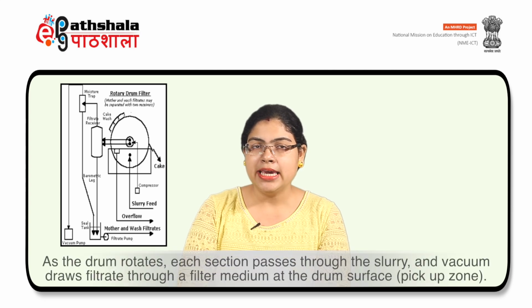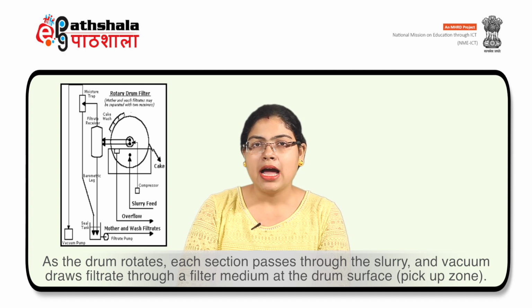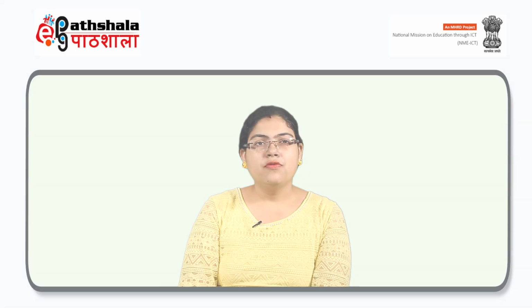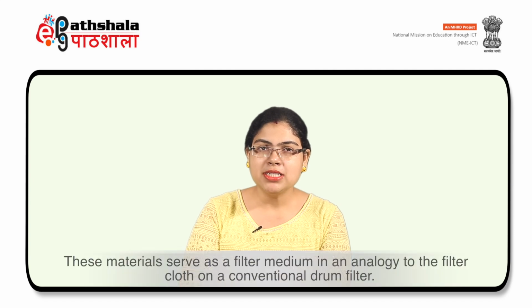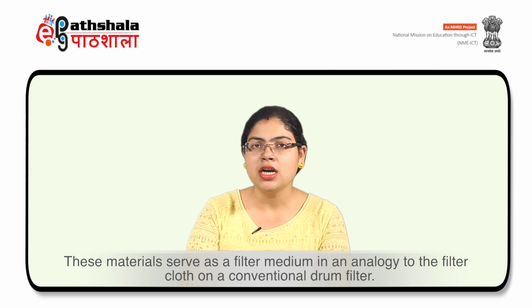As the drum rotates, each section passes through the slurry and vacuum draws filtrate through a filter medium at the drum surface, that is the pickup zone. The suspended solids deposit on the filter drum as a cake, and as rotation continues, the vacuum holds the cake at the drum surface. For solids that tend to block the filter cloth, a pre-coat of filter aid such as diatomaceous earth, perlite and cellulose is deposited on the drum prior to the filtration process. These materials serve as a filter medium in analogy to the filter cloth on a conventional drum filter.